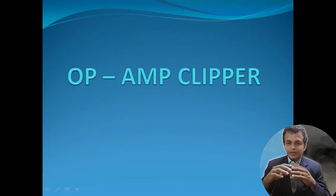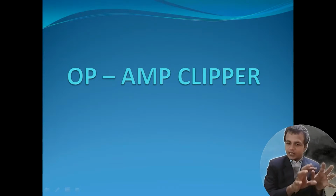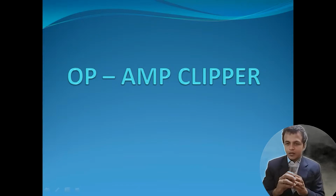If a signal is given to a clipper circuit, then the output of the circuit gives a waveform in which the portion of the input waveform above a reference voltage or below a reference voltage is completely eliminated. Other portions of the input waveform remain the same in the output waveform. This is what a clipper does.